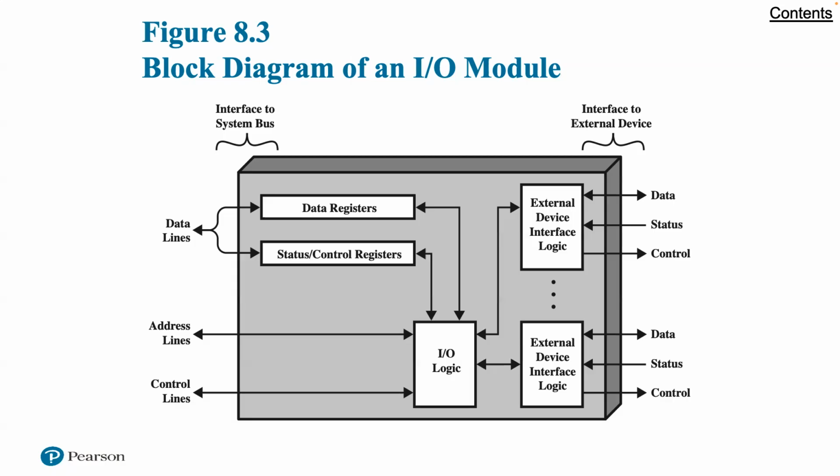An I/O module that takes on most of the detailed processing burden, presenting a high-level interface to the processor, is usually referred to as an I/O channel or an I/O processor. An I/O module that is quite primitive and requires detailed control is usually referred to as an I/O controller or device controller. I/O controllers are commonly seen on microcomputers, whereas I/O channels are used on mainframes. In what follows, we will use the generic term I/O module when no confusion results, and we will use a more specific term where necessary.